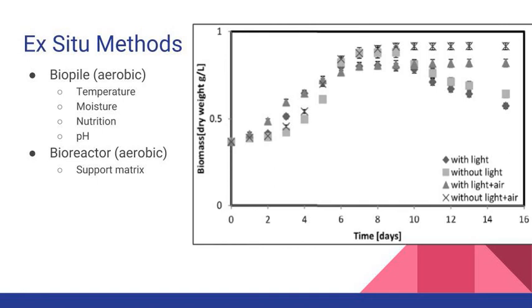Bioremediation through use of biopiles involves placing contaminated, excavated soil into piles and stimulating microbial activity through aeration and addition of amendments such as minerals, nutrients, and moisture. Biopiles are typically maintained at soil temperature ranging from 10 to 45 degrees.